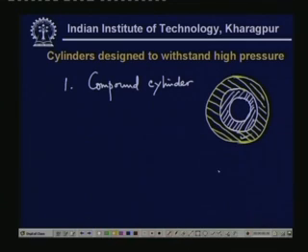What happens for this compound cylinder? Here we are going to see that a compressive stress is developed in the compound cylinder. Now, if the compressive stress is developed, then the material is under compression. So, originally it is under compression, and when we apply the external pressure here, of course the tension develops over here, because there was initial compression. Now, even with tension, the maximum value of the tension does not reach that alarming level. So, this is one way to increase the strength of the cylinder.